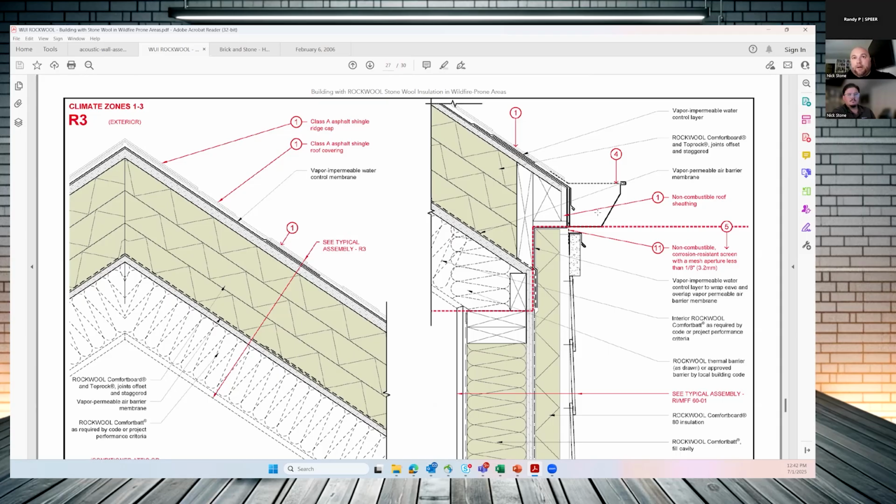Just to piggyback off one of the things you said, what's nice about rock wool is, again, it's cut with a serrated knife. You can put it in, but because of the density of the material, you have to install it correctly, because you can't just go over a wire. You have to physically cut for it and then slide it into that cavity, making it much more effective. So it's harder to cut corners, making it, as designers, what we anticipate it to be, rather than being a little bit less than what we think it will be.